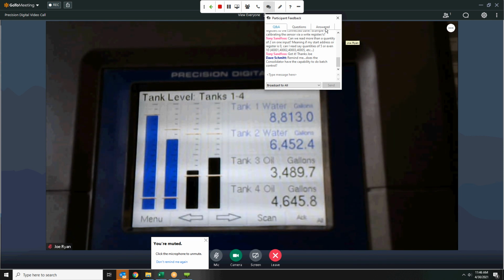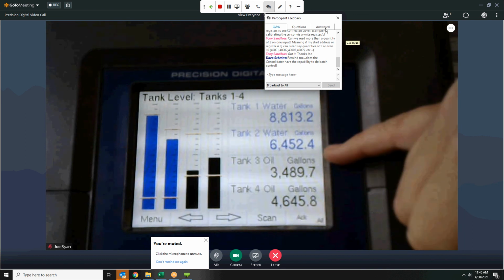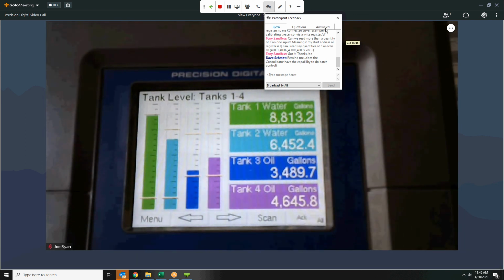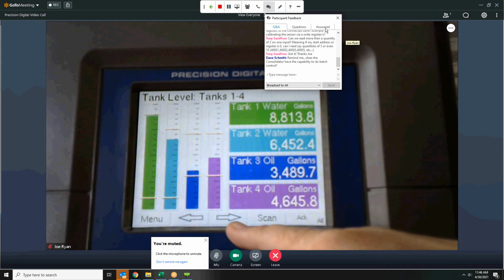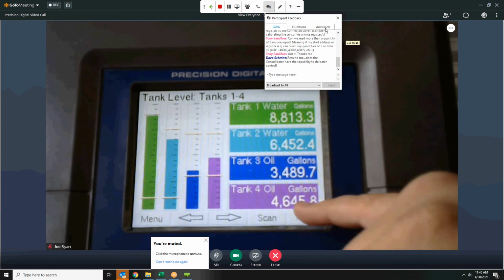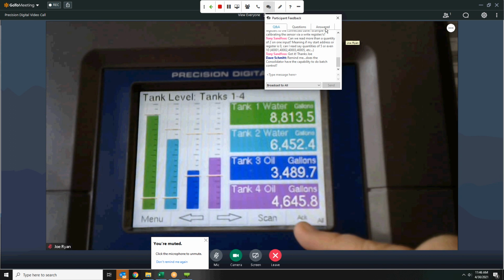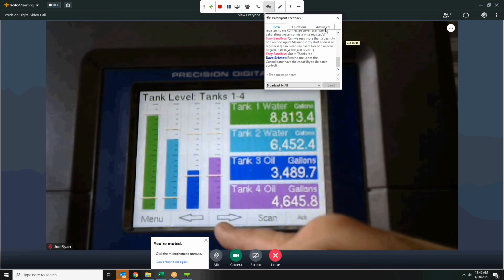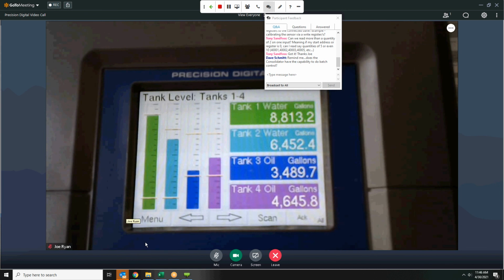And so this looks very similar to the one we saw the pictures of in the slideshow. Here I've got my screen title, my 4 tanks. Actually, we're looking at one that has a lot more color to it, in the webinar earlier. To be clear, by the way, when I'm pushing these buttons, these are soft keys. So it's not a touchscreen display. Nothing happens if I just touch those. But as these are soft keys, you can program them for each screen to be whatever you want, to acknowledge relays, turn on and off my auto scan, cycle between various screens, reset relay information. There's all kinds of things you can do with that. Because of that, that's why they show up down here.